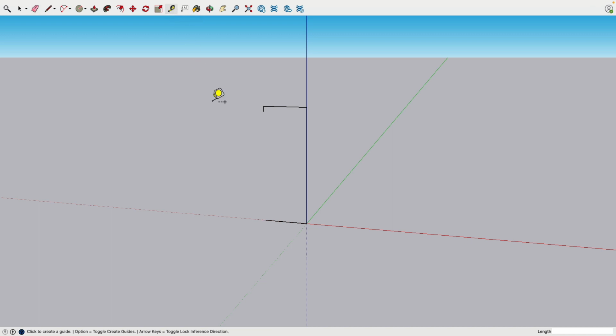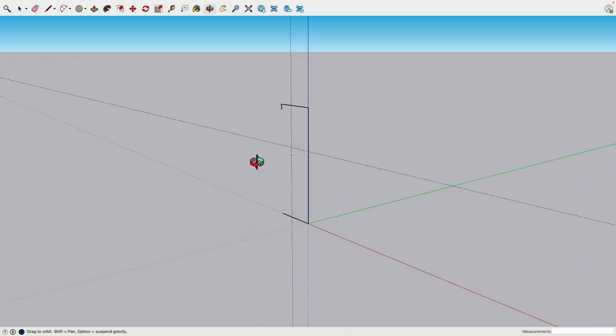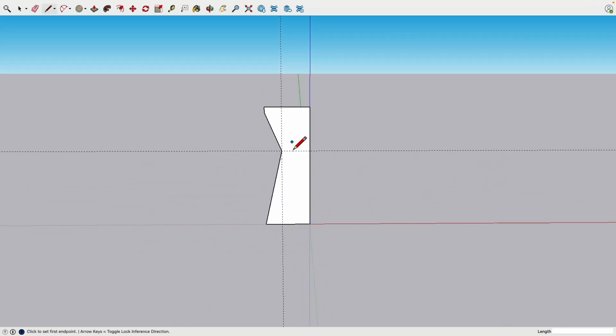We can go to the tape measurement tool. When I go to any edge and I click, I can drag out a guideline. Here we need to have one guideline at the height of 14 inches. And then this vertical one along the x-axis by 5 inches. Now there we see. So think about it like when you take a ruler and you move a guideline. Now we have this point where these two guidelines intersect. Look at this. We can draw there. Zack. And it's filled. Perfect.